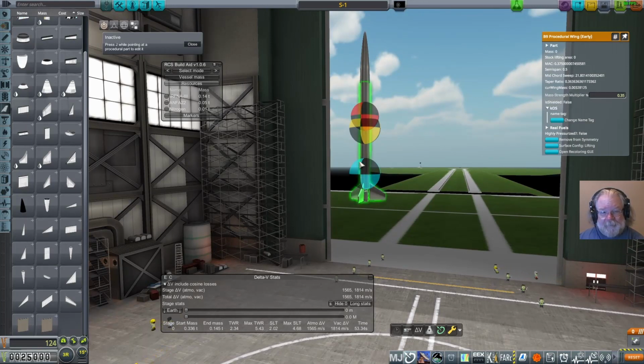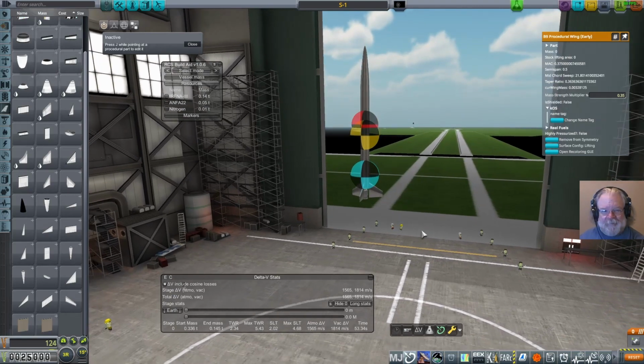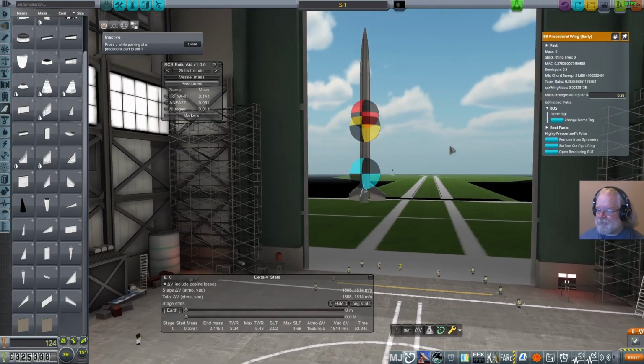So we want the center of mass to always be a healthy distance in front of the center of lift. And nobody ever defines healthy. They all say, oh, that comes with experience. So what you do to get experience is you fly the rocket with a center of mass really close to your center of aerodynamic pressure, and you see what happens. You move it around and you find out where things break, and then you make it separate a little bit more. Or what we do here is we look at it and say, looks good.